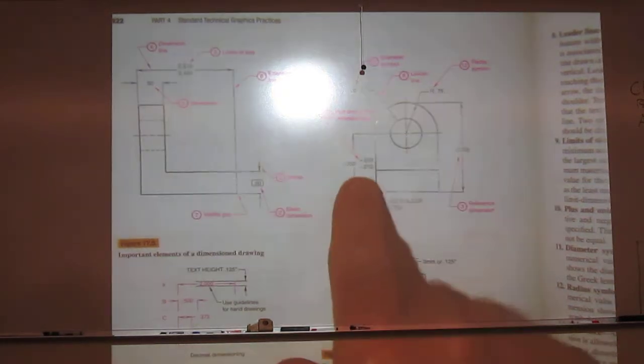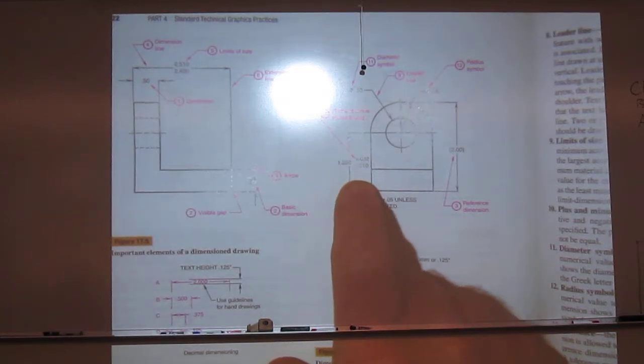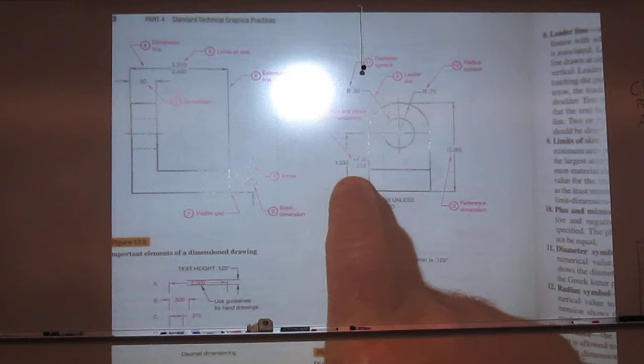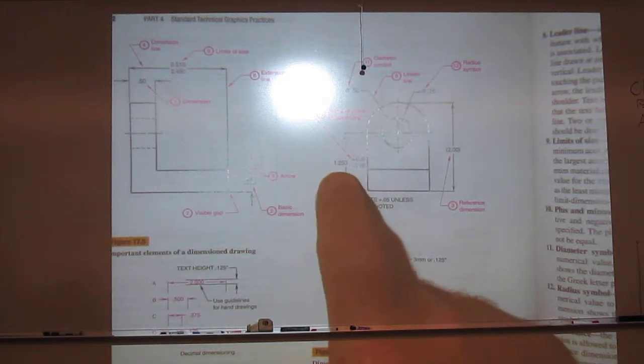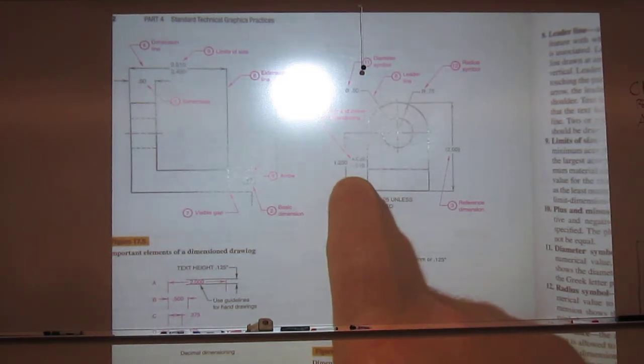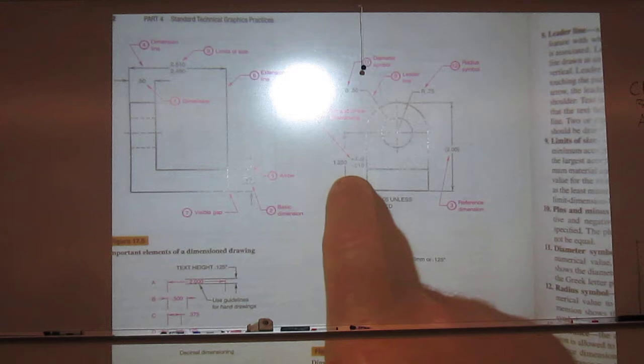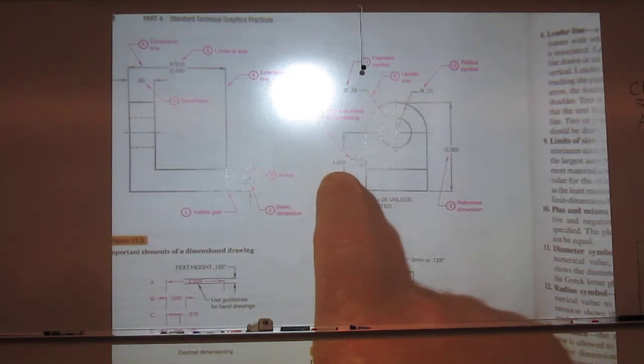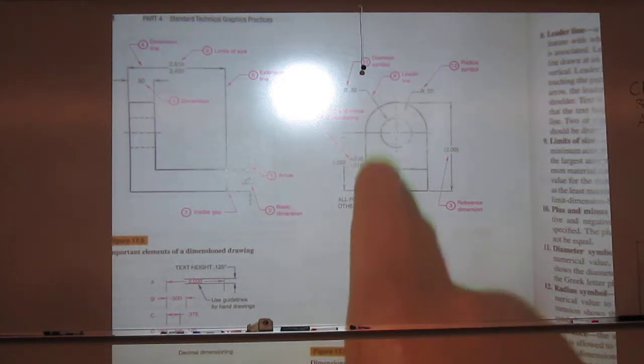As you look at it, now notice that in this one, there is actually a lot more deviation allowed in the positive direction than the negative direction. So in essence, if I'm constructing this, I'm saying, hey, you know what? I'm going to try for 1.25 inches, but I'm going to make the thing a little big if I have an option. So I'm probably shooting for 1.3, somewhere in that, or 1.26, 1.27, right in that range. And that would keep me in that tolerancing zone.